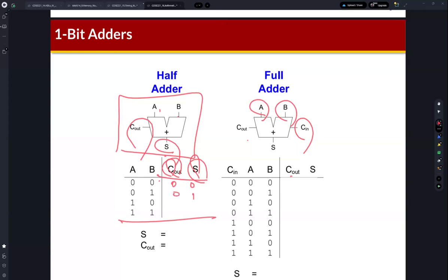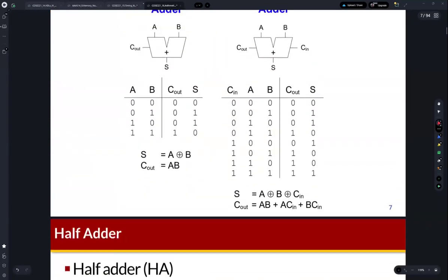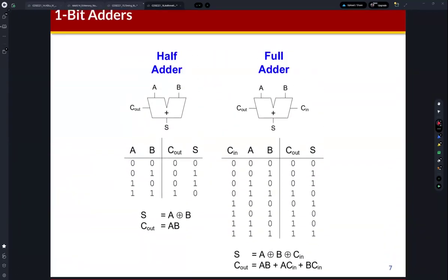The 0. And that's the same, 1 plus 0, so 0, 1. And then 1, 1. So 1 plus 1 is 1, 0, right? So means the carry is generated, but sum is 0. So we can generate the truth table. And then if the truth table is generated, then we can also generate the Boolean equation. Okay, you can identify Boolean equation. It's the same, so you can do this. So this is the answer for the 1-bit adder.